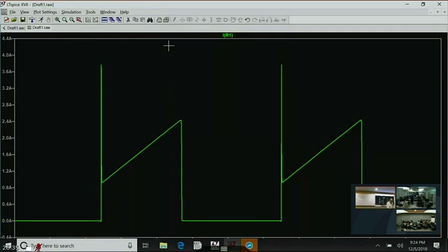And it might work at this point of operation, but say you didn't need that much peak current. Say you only needed that much peak current. Then, because the load didn't need as much current. I mean, if you're powering something besides a hair dryer, the amount of current that the load needs varies depending on what's happening in the product that's being powered. And so then you'd need a very long time constant to make this pulse small compared to that much peak current. And that would give you a very long minimum on time, and that would give you very little dynamic range of duty cycle left to control the output current.